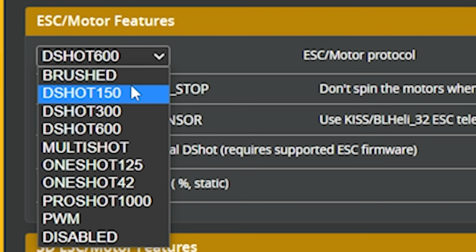But Dshot can do more than that. Dshot can also carry digital commands to do things like reverse the motors that normally would have required you to hook up to the ESC and use a configurator or something. So Dshot carries the throttle signal and Dshot commands, which can tell the ESC to do certain things. Now, the 3 variants of Dshot, Dshot 150, 300, and 600, relate to how fast the packets are sent.